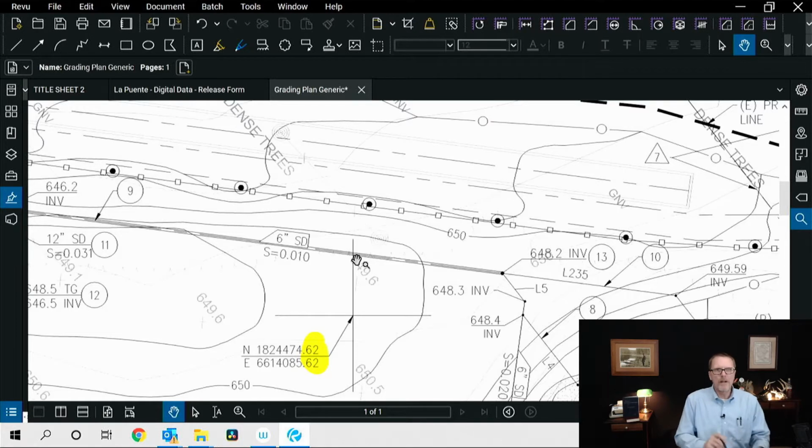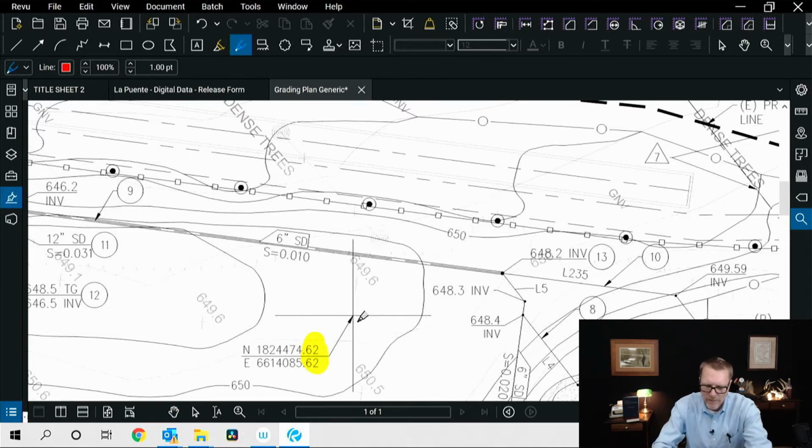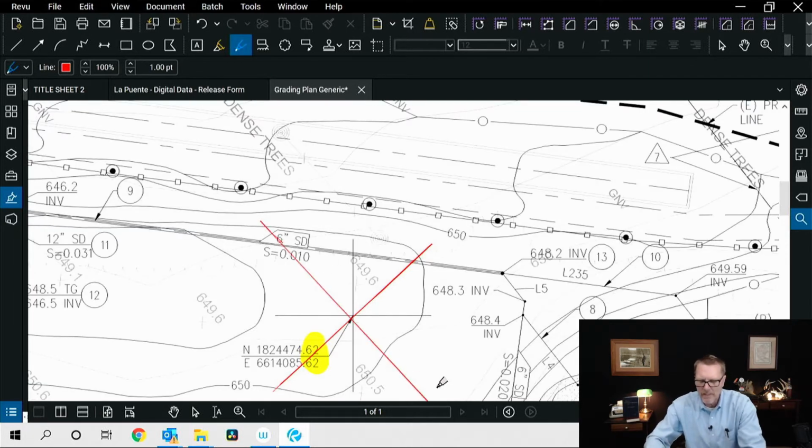that this is a bunk set, is you see that north's at 45, and look how the grid tick runs. It runs to the top of the sheet and the bottom of the sheet. A real grid tick done at the time, intended for use, would actually look like this, because it's supposed to run north, south, east, west. Why? Because you're scaling in northings and eastings for staking.